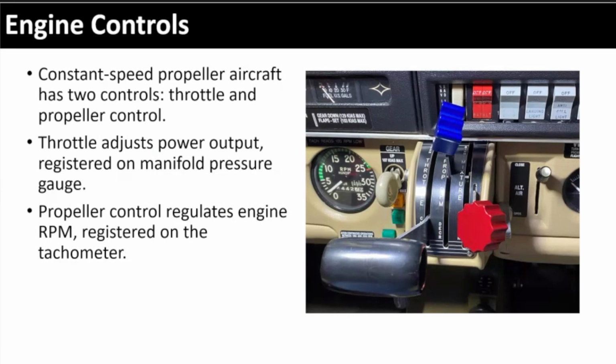As you increase power, or increase or decrease altitude, your prop speed is going to stay right where it is. I'm getting way too much detail here. This is what I didn't want to do. So there's no specific control to change the pitch of the prop. It happens automatically based on the RPMs. Is that correct? Yes, you set the RPMs and the system, the hydraulics and the governors and everything back behind the black curtain, will adjust the pitch of that blade to maintain that prop speed.